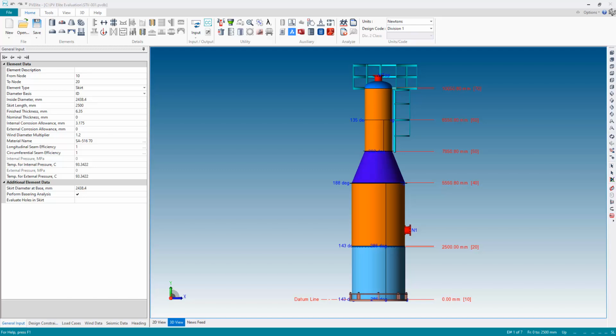Okay, now the final stage. Now that our analysis of this pressure vessel is complete and there are no issues, the final thing to do is to generate the report. I've already run the analysis, but I'm going to run it one more time. But before running the analysis, I'm going to hit this button here to generate a 3D PDF file. This will allow me to include a 3D page in my output report, which helps to give everything a little bit more context. So I've hit the button to turn on create 3D PDF files, and I'm now going to hit analyze for one final time.